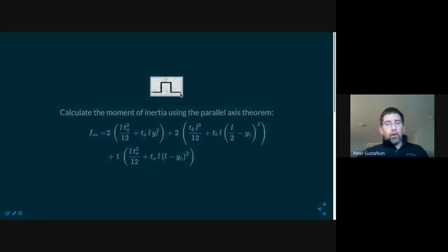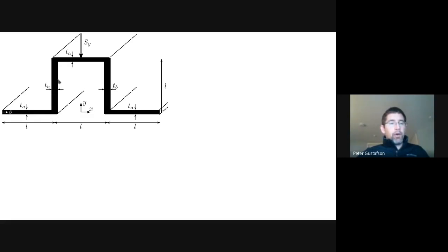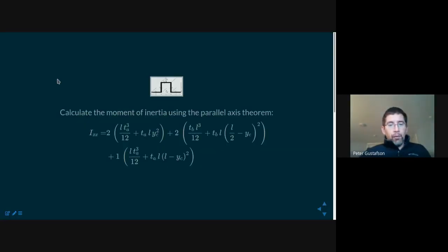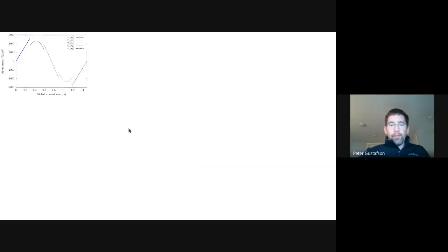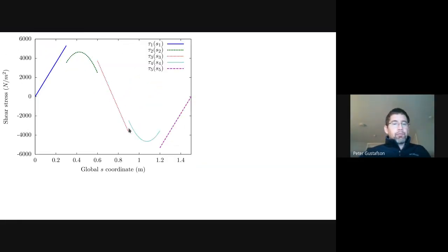that's this beam here, of course, we see that there is a discontinuity in thickness. It's one thickness here and then a step change in thickness there. Because of that, we would anticipate a step change in shear stress. If we look at this plot, we see that as we go around that corner, we actually get a step change in the calculated shear stress.